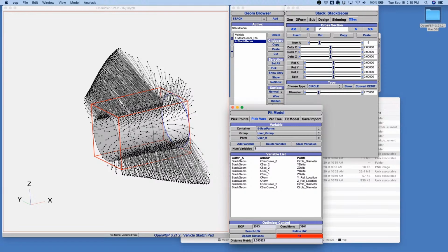You don't need a super detailed laser scan with a gigabyte of points to do a fit. You really just need a few points in the right locations, and fewer is better in a lot of ways. The way the algorithm scales, it does get more computationally expensive with more points, but what's more important is how well posed your optimization problem is, i.e., does your optimization problem blow up, or is there a very flat optimum where it can't find an answer, or do you have two of the variables that can be used to accomplish nearly the same effect?